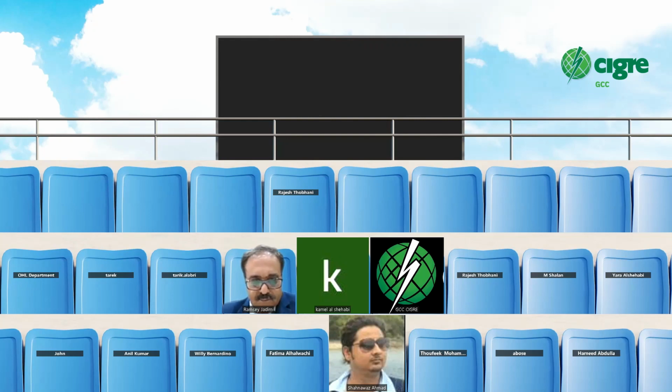I have a question for Dr. Ramzi. Thank you for the informative presentation, Doctor. We have a lot of transformers with a thermal fault, which is exceeding 600 or 700 degrees Celsius, where the other gases are within the normal limits. And actually, there is no clear action what need to be done, especially for the thermal fault.